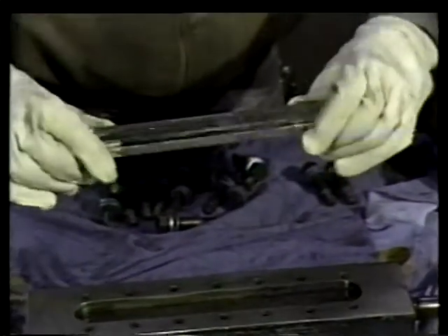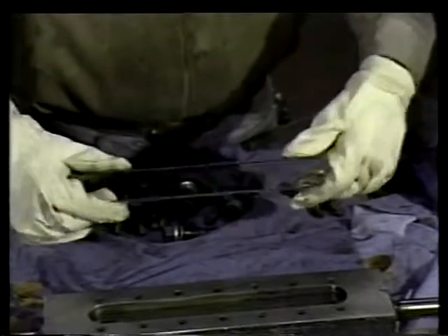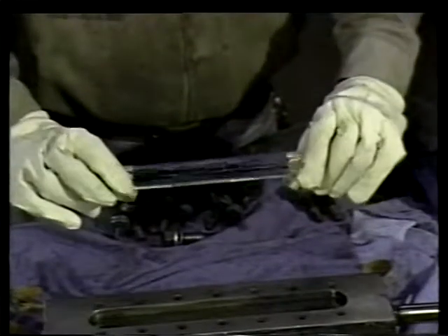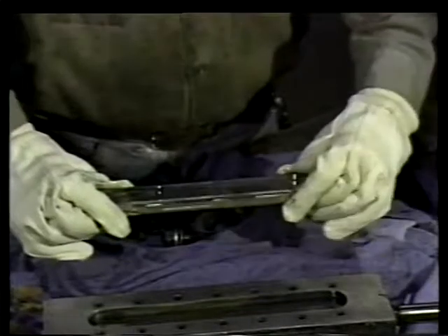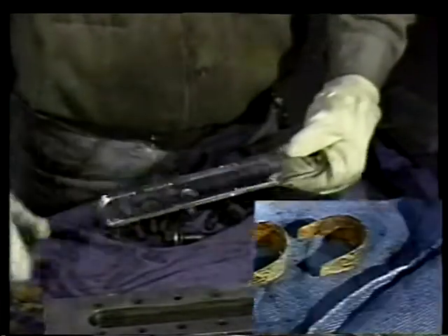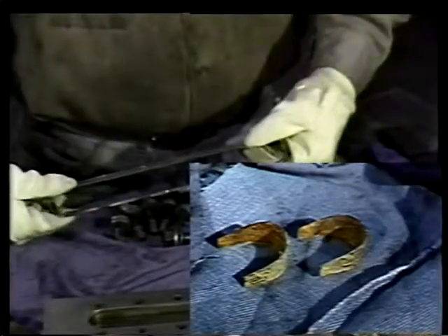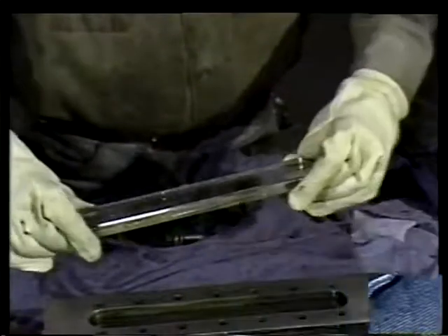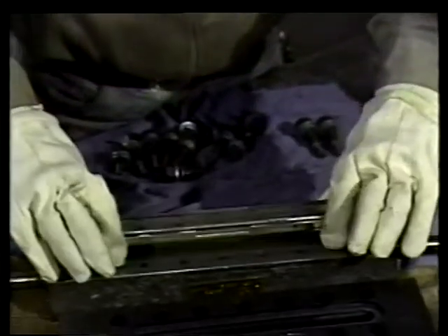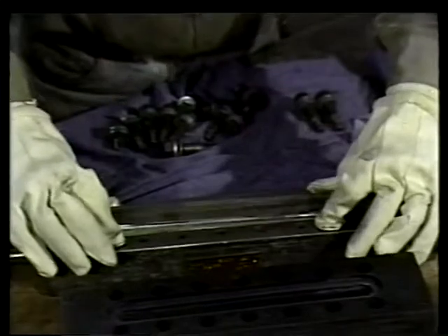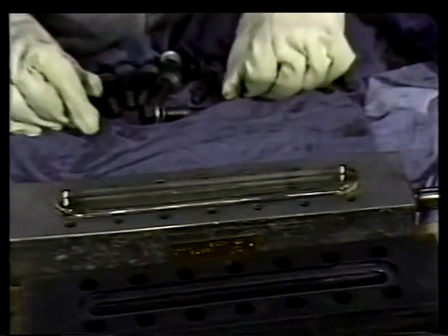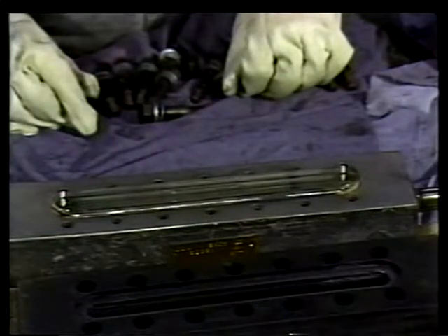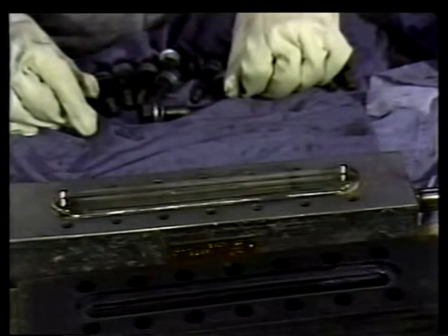Check the glass one last time to be sure it is clean and free of scratches. Even a fingerprint could etch into the glass. Place spacers, pieces of gasket material, at the ends of the glass. Center the glass over the mica so that the glass evenly clears the sides of the recess. The spacers will prevent contact with the gauge body and help center the glass.